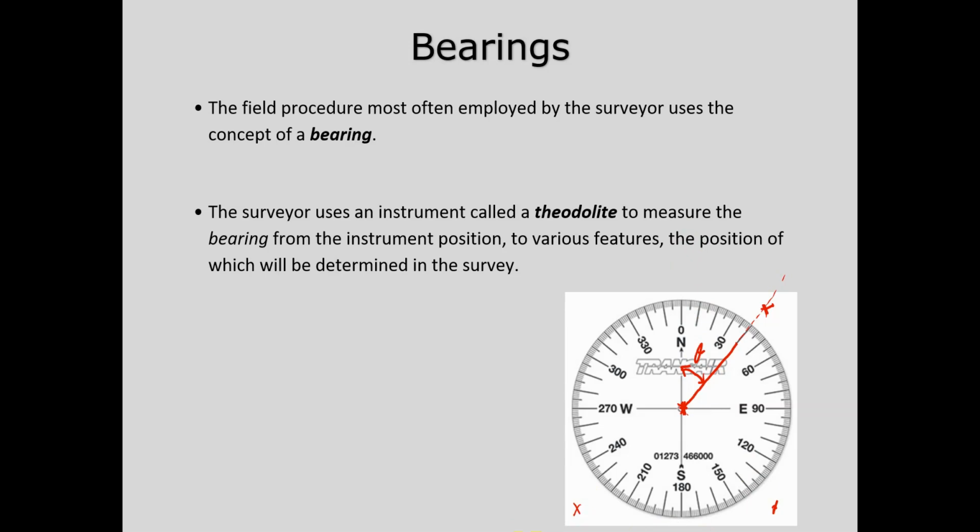Let's go into details of how we deal with bearing, why we use bearing, and how we are going to utilize it in practical examples. The information we usually deal with, from our point of view as engineers or designers, is survey information. The surveyor on site will be specifying the starting point and the end point of a linear segment, specifying the bearing angle and the length, and sending us that information. So our job, if we have this information, is how can we describe it on the plan, or how can we draw it in very simple terms?